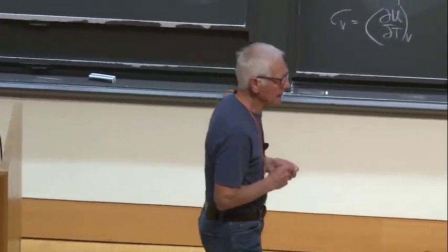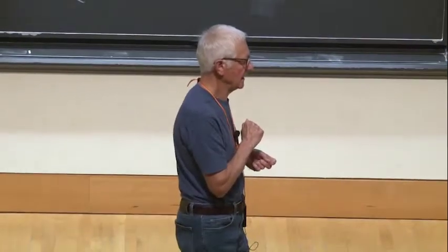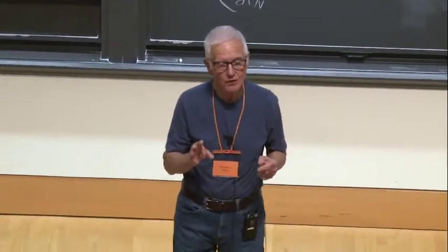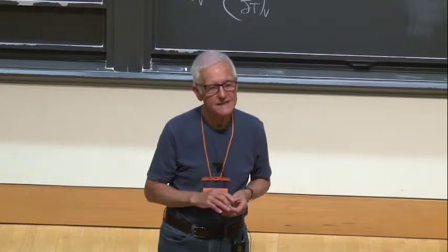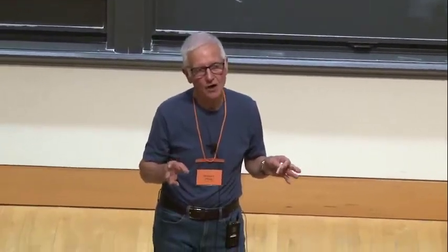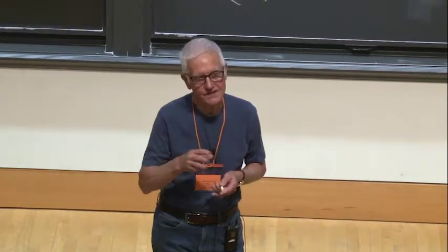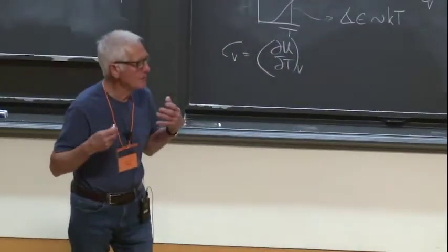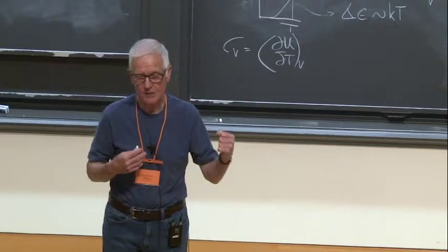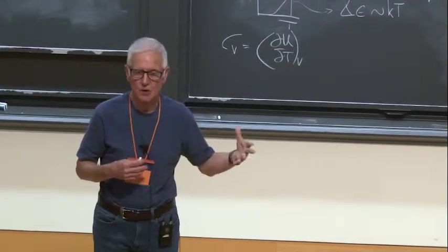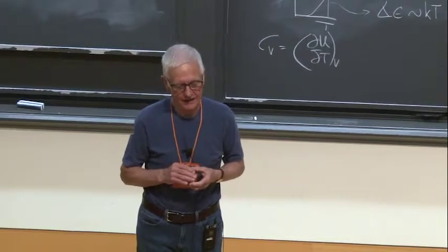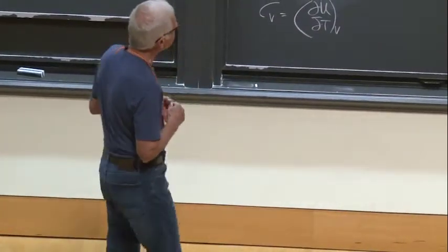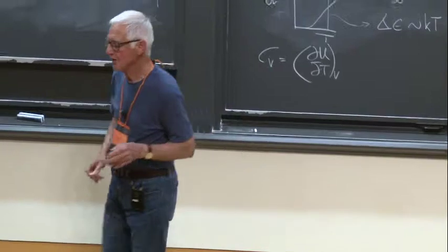Okay, it struck me when I'd done this, I was thinking about it last night and thinking about some of the comments from one of you yesterday, that it might be worthwhile saying a little bit more than I've done so far about heat capacities and energies associated with different forms of motion. Because we need to understand energies and heat capacities if we're going to predict what enthalpy changes in a combustion system are going to be as a function of temperature. We need those heat capacities. Okay, so let's fairly quickly just go through this on the board.